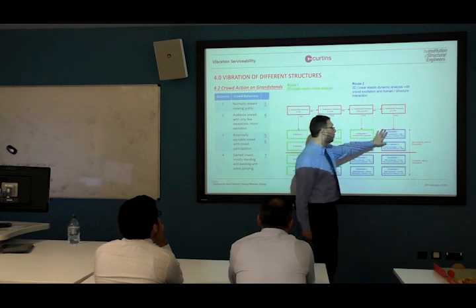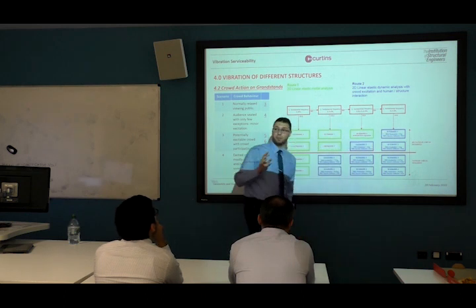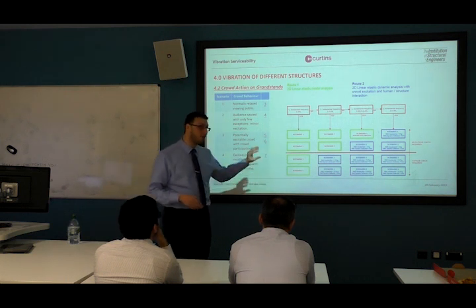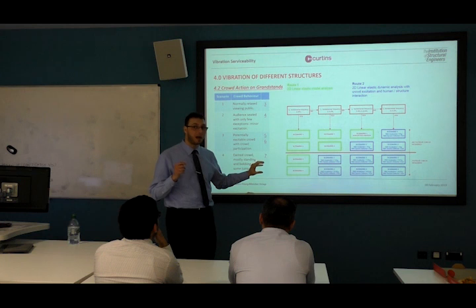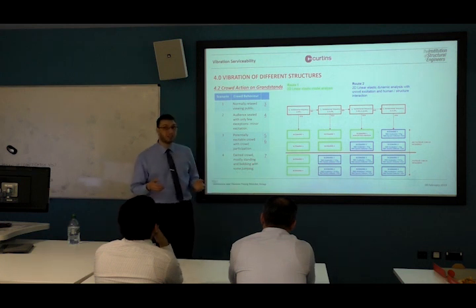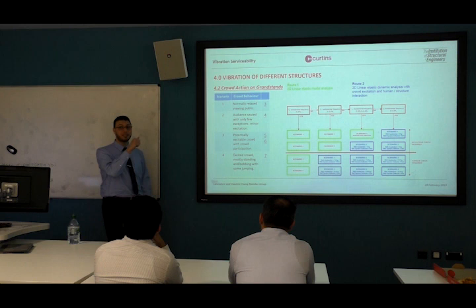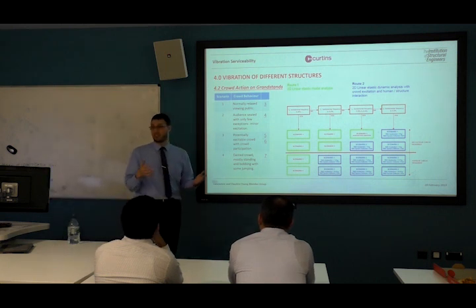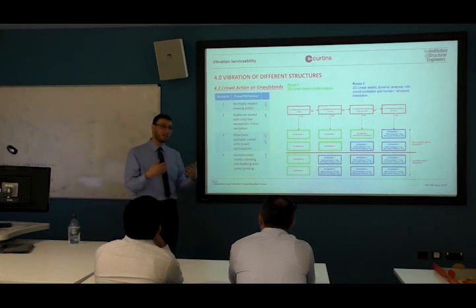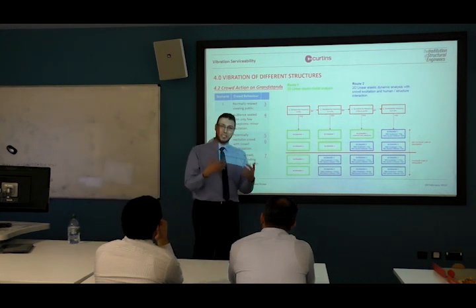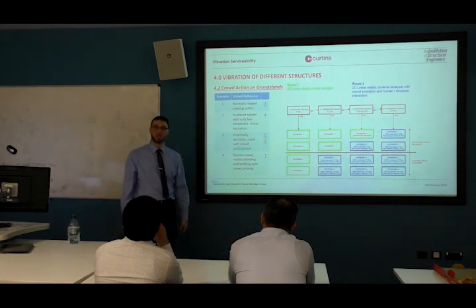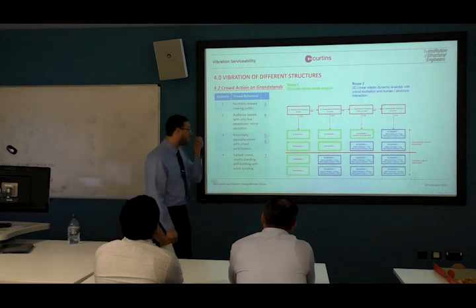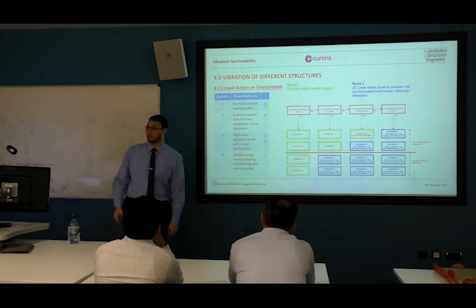If you have scenarios 1 and 2, this is not causing a problem to the ultimate limit state of the structure. But if you're having scenarios 3 and 4, you have to think about whether the structure is able to take this load. And I think we've seen from the second video that the structure was actually about to fall down. The structure was really excited, and supporting the fans as well. So it wasn't the best view you can see as a structural engineer. Maybe for fans, it's all right.